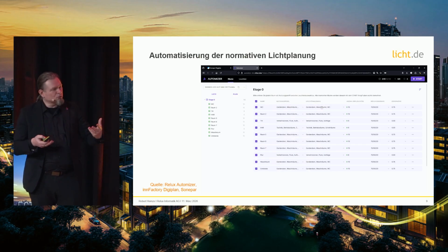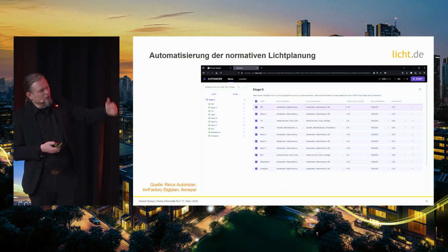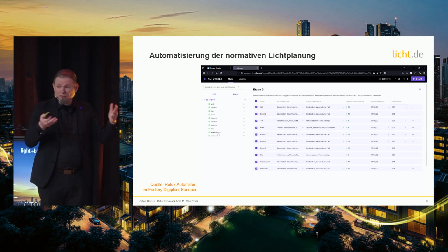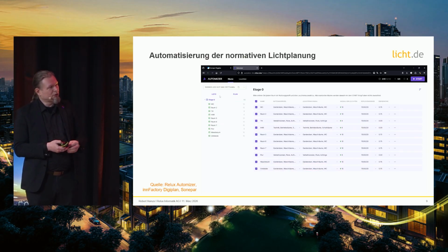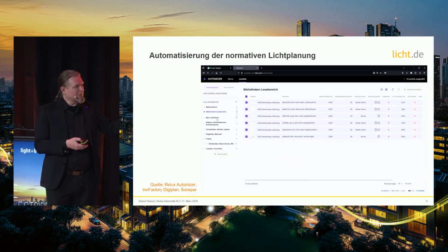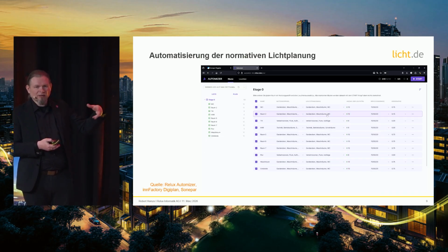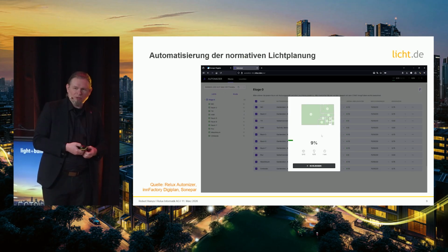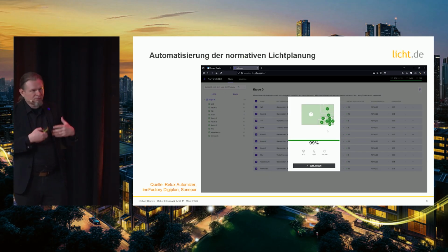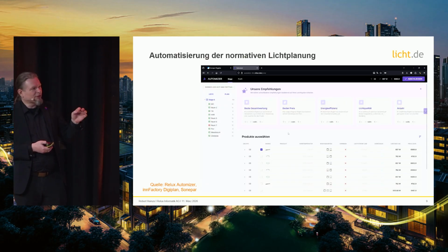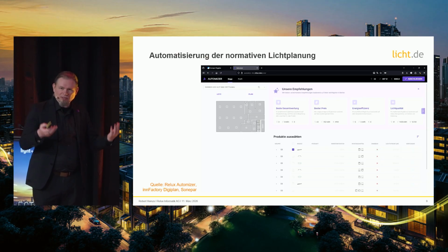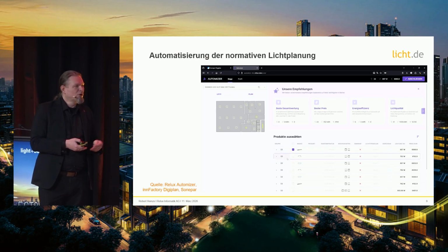This is the pre-filter. Each room has been allocated a usage. I've done this in this case. And then we have luminaires which match this usage. We have a standard set for Sonepar for corridors, one set for all toilets, and these are allocated to these profiles. You can do it yourself also. You can pick luminaires which you'd like to have for a toilet. It must have a certain color temperature, a certain size or a certain price or something. I can pre-select it. And then the computer does thousands of computations with the Relux core.